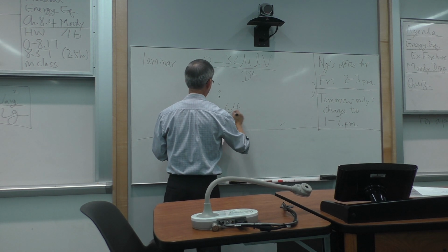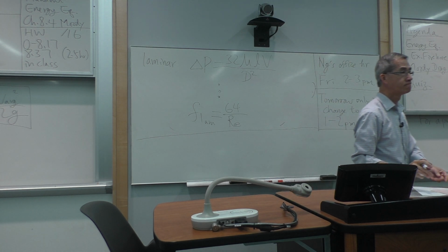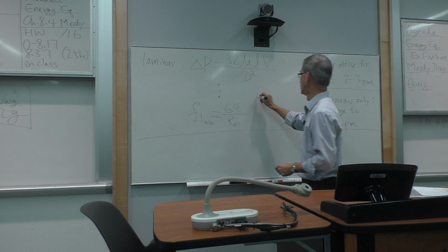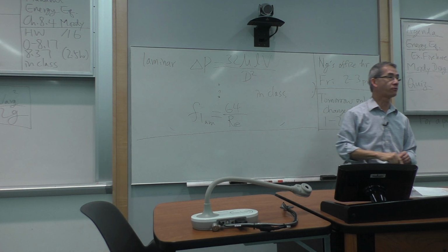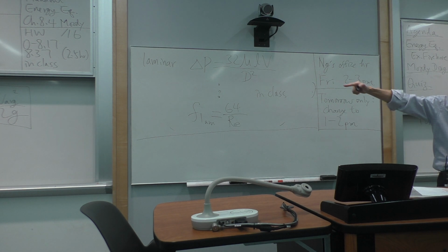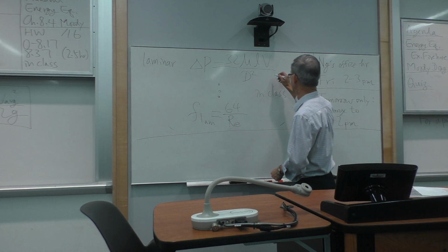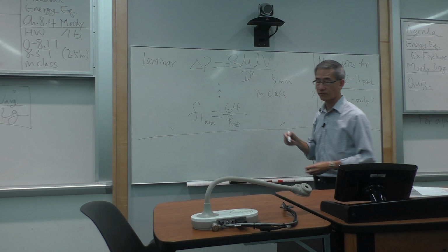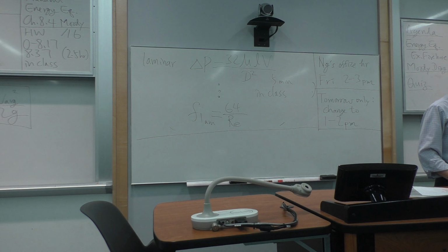Through half a page or less of algebra, 3 or 5 lines, show me that for this given pressure drop for laminar flow, when you work through the algebra using the equation I posted, the friction factor is 64 over the Reynolds number. Right, this is the 5 minutes homework, not 5 hours. Whenever you're ready, you can start your quiz.